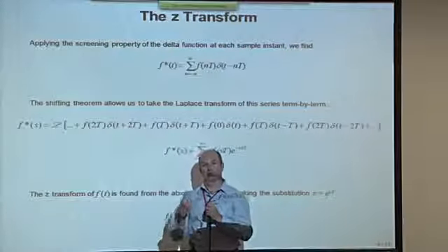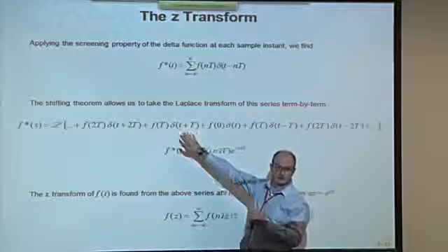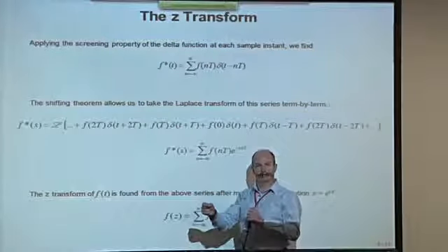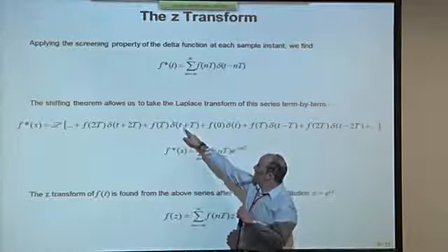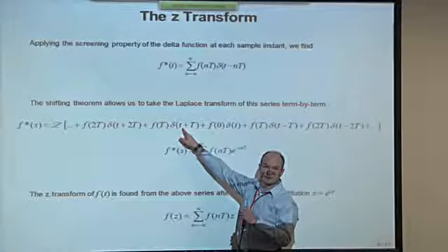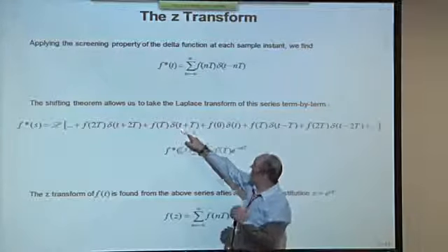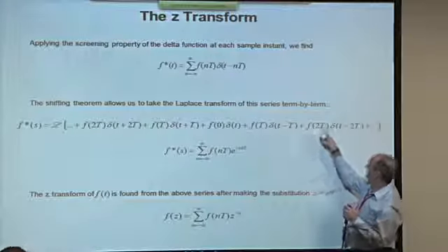It has a unit area, it's always 1. So what I have here is a series of transfer functions, all of which are 1, but they're time shifted. By the time shift property of the Laplace transform, this, for example, would be e to the 0, this would be e to the minus sT, and so on.